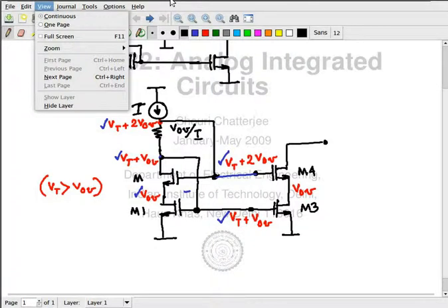Bad news because of the resistor is first because you need an additional mask. An additional mask increases costs, reduces yield, and is bad news in general. The boss won't be happy that you need a resistor. The other bad news over here is that you need a specific value, which is VOV by I. And we hate talking about specific values.